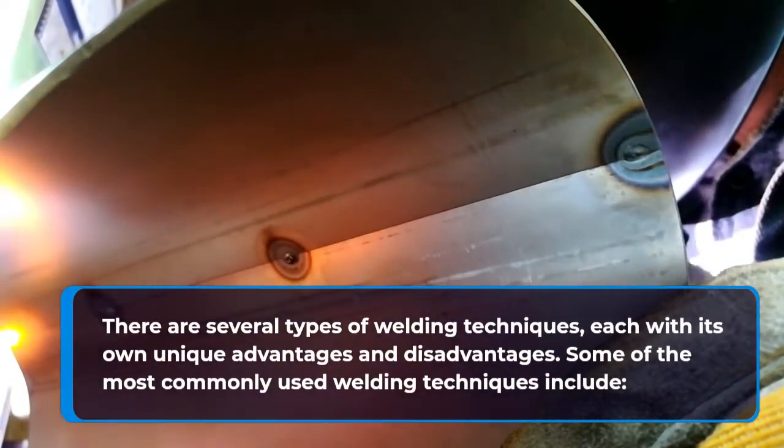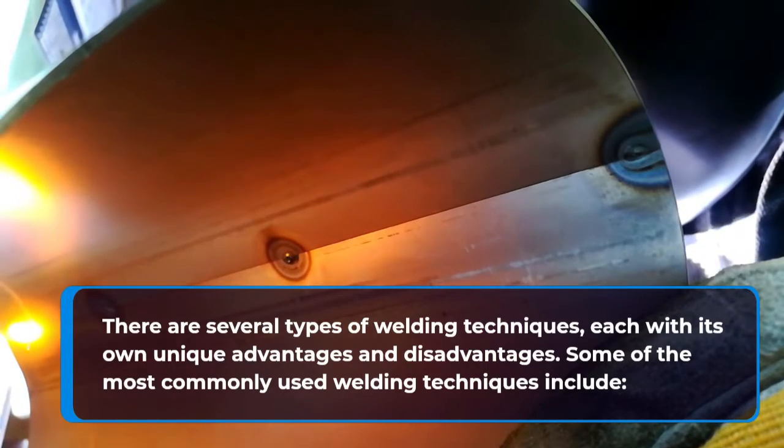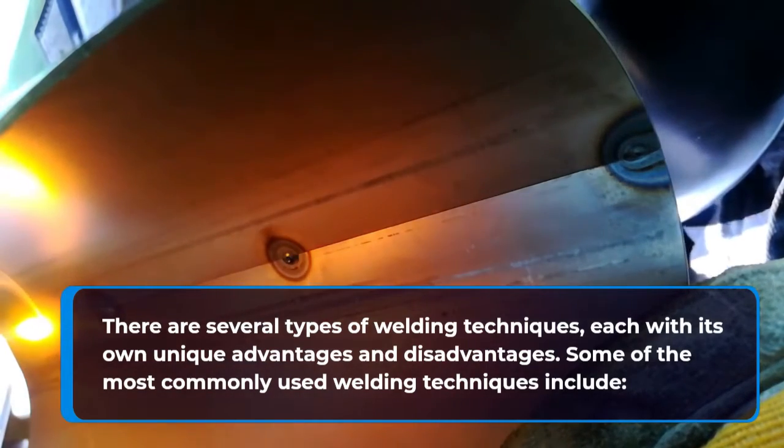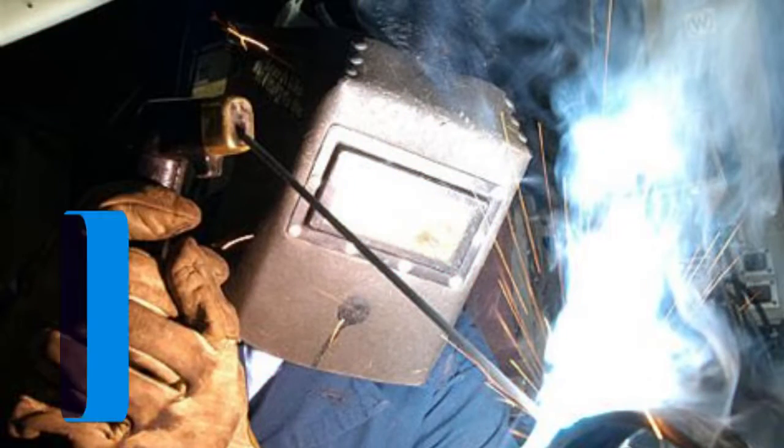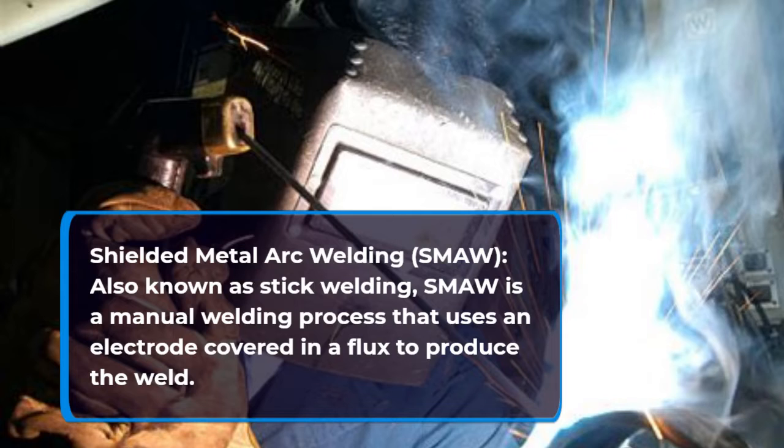There are several types of welding techniques, each with its own unique advantages and disadvantages. Some of the most commonly used welding techniques include shielded metal arc welding, SMAW, also known as stick welding. SMAW is a manual welding process that uses an electrode covered in a flux to produce the weld.